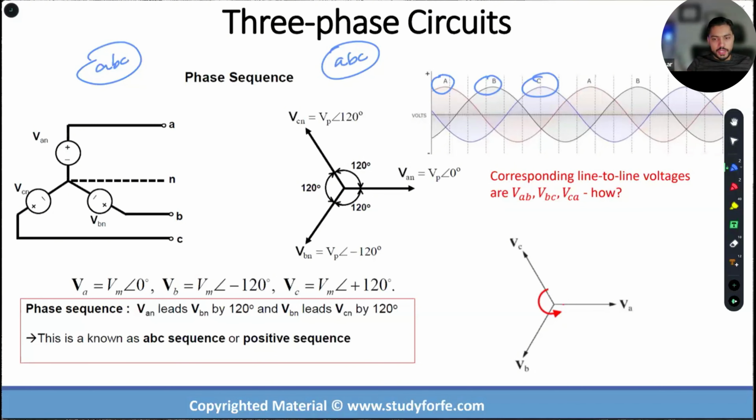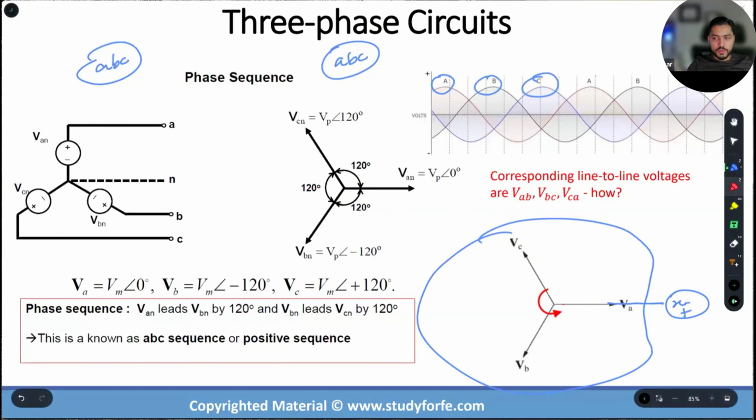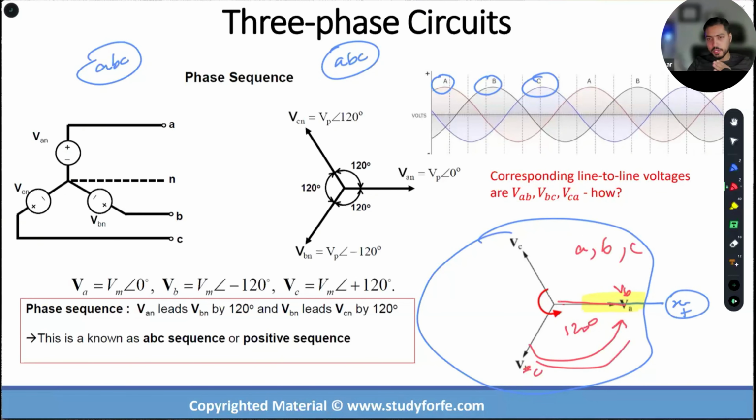All right. In terms of phasor representation, with a counterclockwise rotation, which is always assumed, from a positive x-axis standpoint, okay, reference is our positive x-axis. You will have phase A first. Now imagine me giving it a 120-degree twist. So after A, what am I going to see? B. Now B is sitting over here. B is being followed by C. Another 120 degrees, I end up with C. ABC, ABC, ABC. Clear? All right.